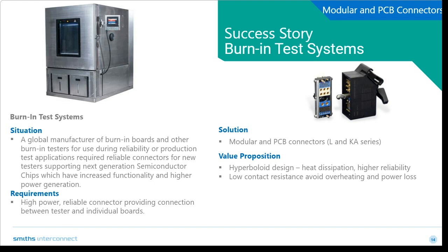They've chosen these connectors because of the hyperboloid contact and all the different benefits it provides, including the higher current carrying rating, the lower contact resistance, and the very low insertion and extraction force.